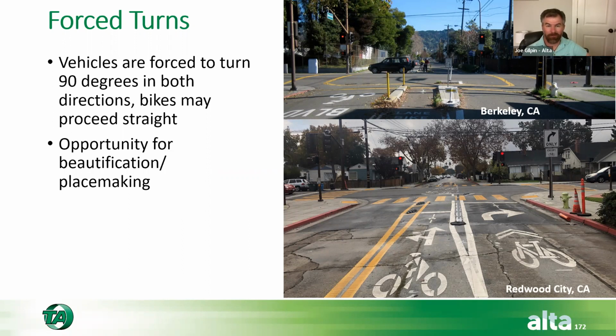But a lot of communities around the country have adopted this. It works really well. It allows you to have signalization, get bicyclists through, but block this as a cut-through for motorists. A lot of times, if you have a good grid and any issues on the public involvement side of getting this installed, as long as there's good connectivity, you can just show them, hey, you just need to go a block upstream or downstream, and you can make your left turn there or go across. Those are areas where it's pretty easy to do. We were able to message that in other projects, and the public was pretty accepting, got what we were trying to do, and enjoys the new signal that enables people on foot and bike to cross a busy street. So those are all things that work really well.